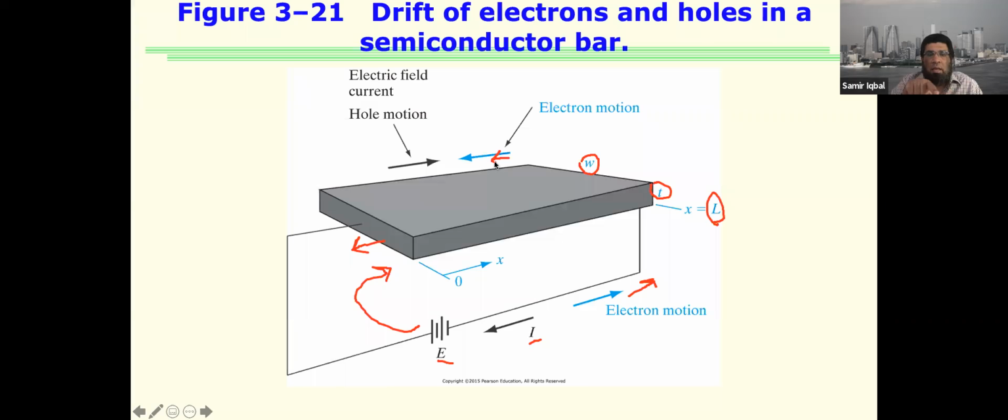You may be confused because in circuits, we take the current to be coming out of the positive terminal and going to the negative terminal, right? And here I'm showing you something opposite. The difference is here we are talking about the movement of electrons. That's it, movement of electrons. So when you talk about movement of electrons, it's taken in this direction. And we are talking about electronic current here, whereas in circuits you talk about conventional current. Those two concepts, don't get them confused. When you talk about electronic current in semiconductor devices, we take that to be opposite of the applied field or applied voltage. All right, so if you get these things in place and we take the whole motion in the direction of the applied voltage, we find basic relationships.